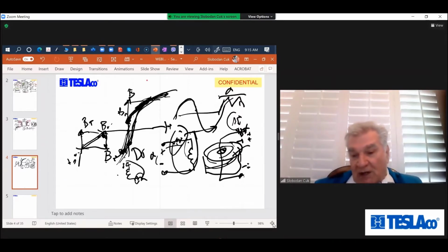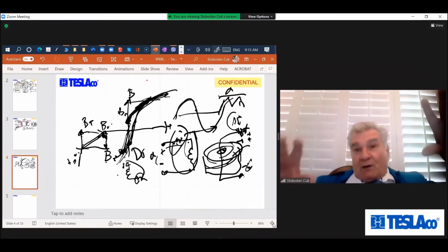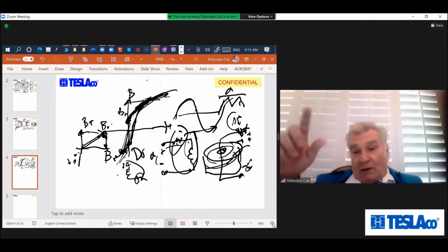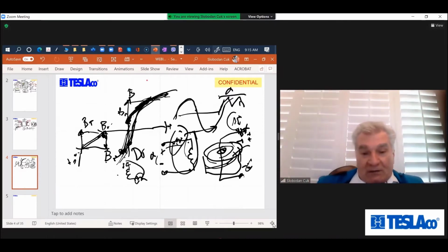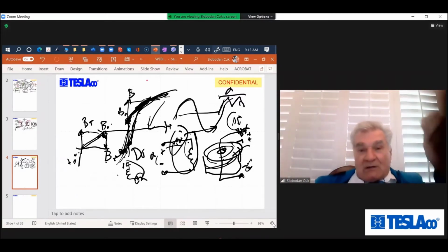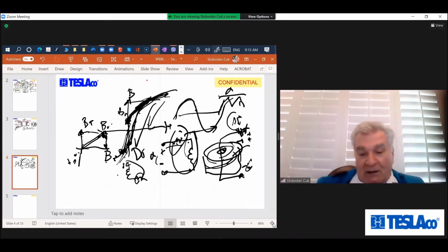You can use this as a sense winding, and if you drive a transformer in one direction, like you started from here, driving in one direction, you can stop driving it in that direction because the sense winding will tell you how close you are to saturation, and you will drive devices in the opposite direction to drive the flux in the other direction.